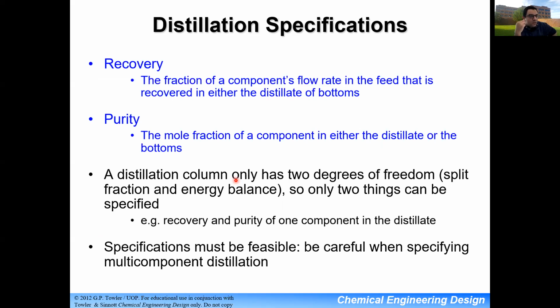And you'll feel this a lot more when dealing with Aspen, where, as we start dealing more with these distillation column separation equipment, you'll find out that they're harder to converge and always give you a bunch of errors. You have to be very sensitive with the thermodynamics. Okay.